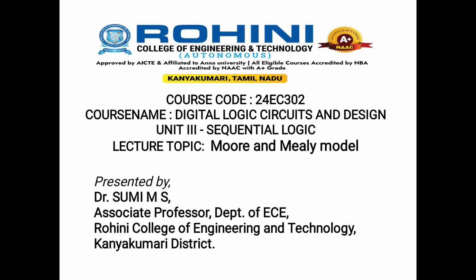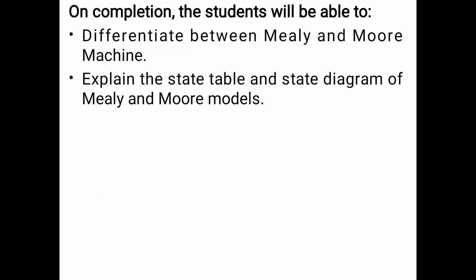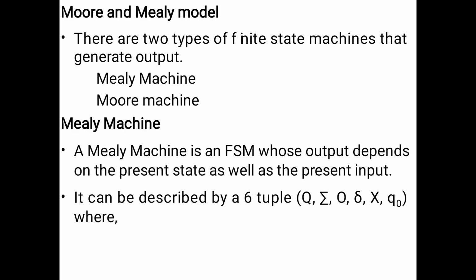Sumi MS. The topic of my today's presentation is Moore and Mealy model from Unit 3 Sequential Logic of Digital Logic Circuits and Design. On completion, the students will be able to differentiate between Mealy and Moore machine and also be able to explain the state table and the state diagram of Mealy and Moore models.